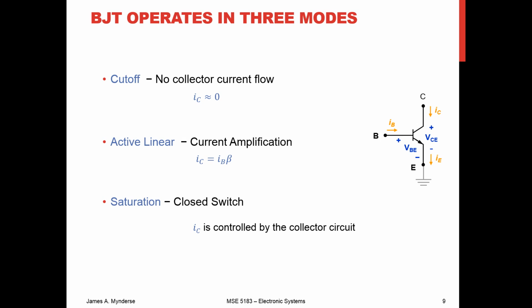Now, as I just start to open the valve and allow water to flow, as I open the valve a little bit more and a little bit more, the water flow increases. And so you see that the sprinkler starts spraying further, and it's proportional to how much I've opened that valve. Up until I get to the point where the valve is fully open, and now the limitation is the hose, the limitation is the piping, and so I can keep opening that valve, but it's not going to do anything.